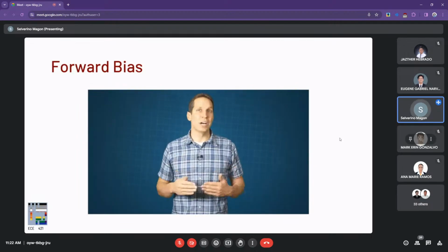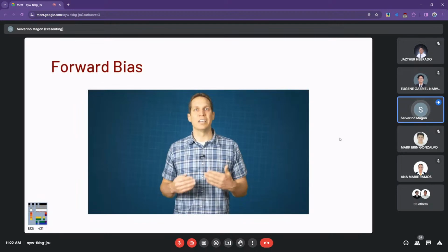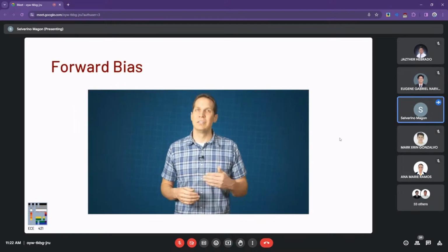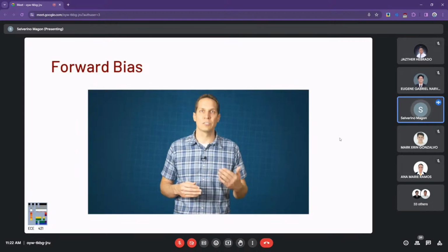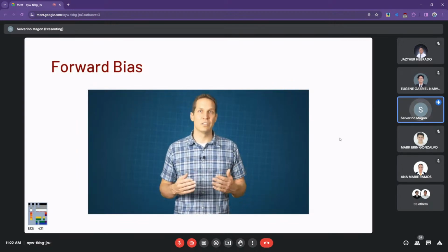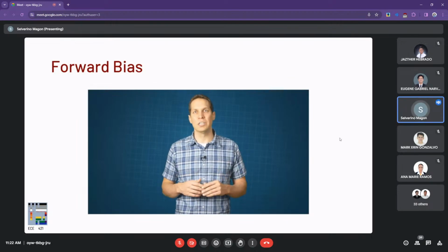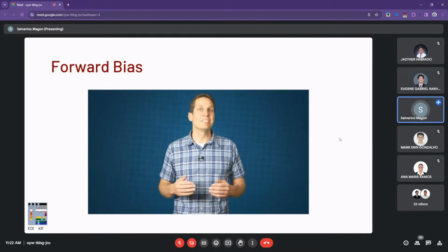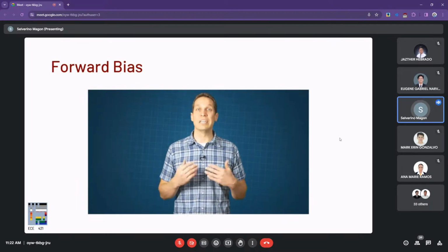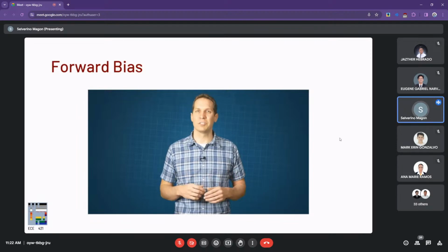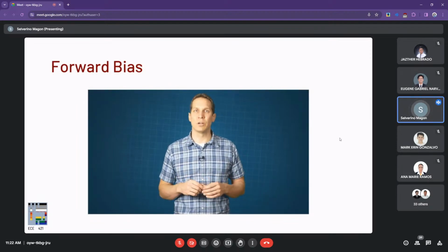When a diode is forward biased, the external bias voltage provides energy to the free electrons so that they can overcome the barrier potential. These electrons give up an amount of energy equal to the barrier potential when they cross the depletion region. As a result, there will be a voltage drop across the p-n junction, which is usually around 0.7 volts, and an additional voltage drop due to the internal resistance. The internal resistance is called dynamic resistance and is usually ignored since it's very small. You will notice this voltage drop due to the barrier potential when you start working with diodes.